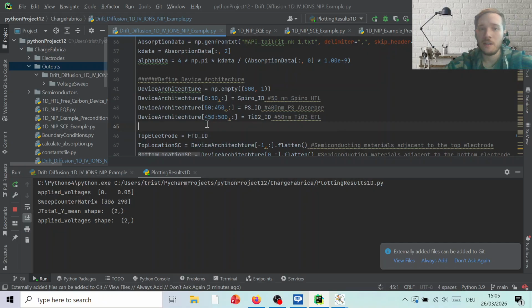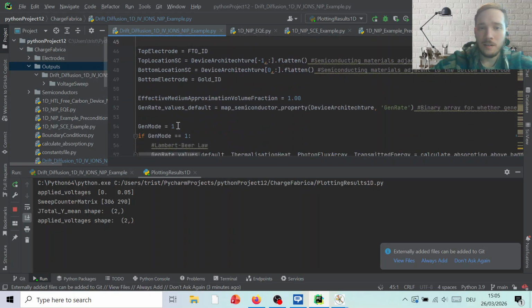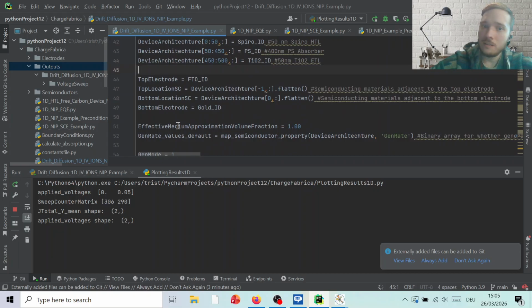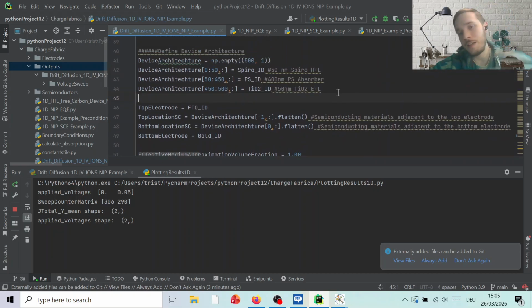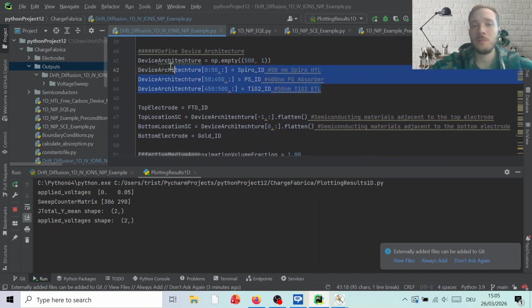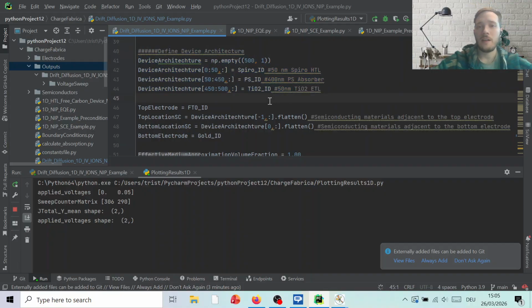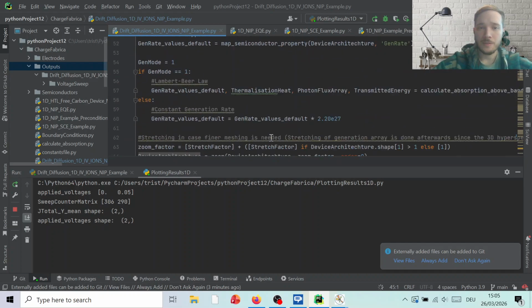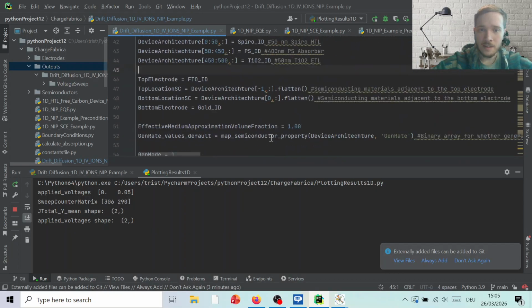I generally recommend ideally running this on a dedicated computing cluster, because especially the 2D simulations can quickly get quite computationally intensive. At the beginning, it's best to start testing a simple 1D problem first and make sure it works in 1D before moving on to a more computationally intensive 2D problem.